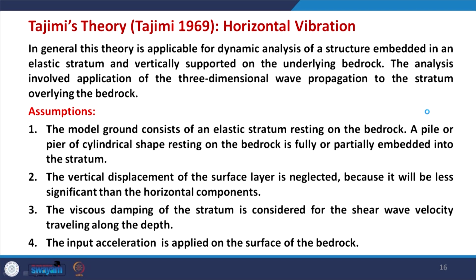In general, this theory is applicable for dynamic analysis of a structure embedded in an elastic stratum and vertically supported on the underlying bedrock, which we already discussed. The analysis involves application of 3-dimensional wave propagation to the stratum overlying the bedrock, so it is not a plane strain condition.